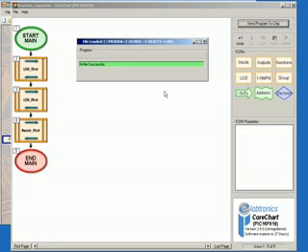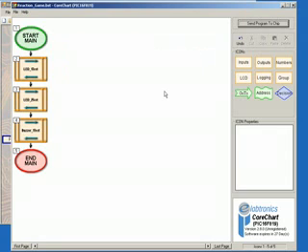and to run the program, simply push the push button switch on the controller board, and the red LED will turn on and then off, the green LED will turn on and then off, and the buzzer will turn on and then off. This completes testing the hardware, so we can now begin to create our main program by firstly deleting these test subroutines by clicking on icon 2.